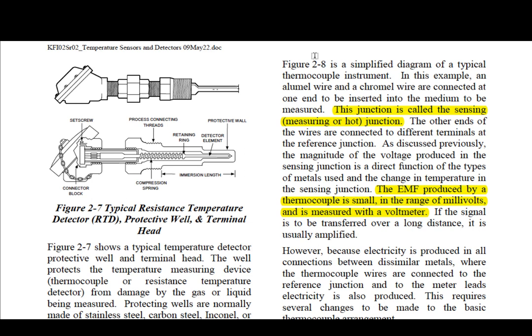They're calibrated correctly. What it is, the unique property that comes out of the reactor vessel is that there is a laminar flow going through the pipe, and that laminar flow has different temperatures based on different locations within the pipe itself. The water, the heated water, doesn't actually start mixing till it gets over to the steam generator, which is pretty interesting. So when you're in the control room, you're going to see the monitors for these 3 thermocouples, and each one of them in that circular pattern is going to have a different temperature, but they're going to range fairly close. That's why we have what's called T average.